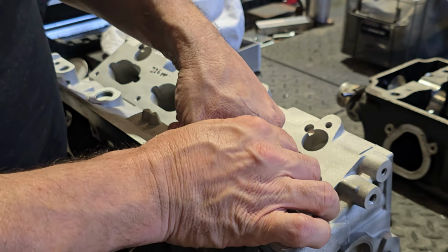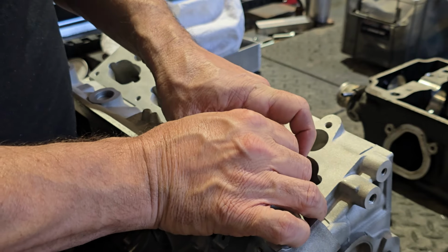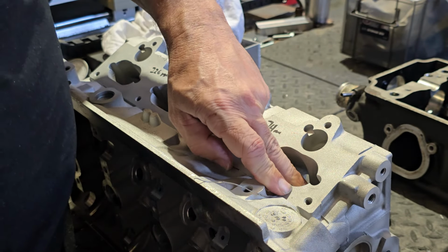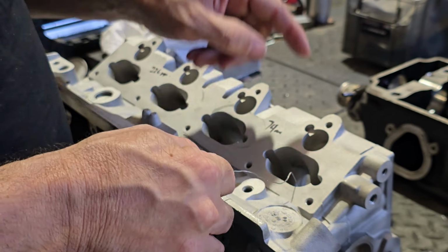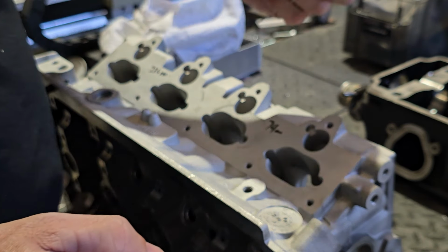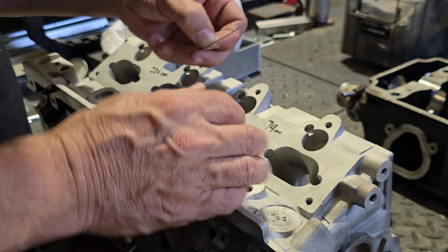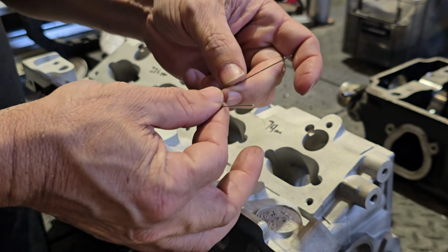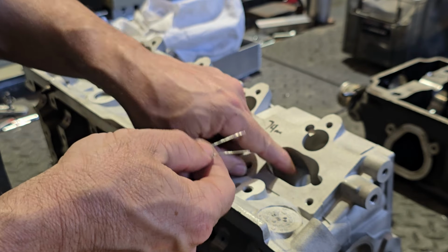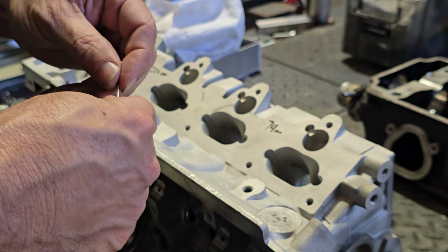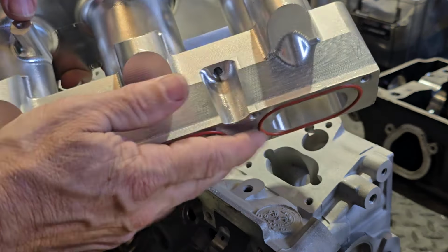So all I do is set it up on the bottom of the seat, and if you press it into the casting, it'll form itself, and then you can just bend it over like so, and then you've got the port shape. So we're going to do the roof and the floor. I've already done that now, so that's our roof length and our floor length. So we add those two together and then divide by 2, and that gives us our port length, which came up at 74 millimeters. Then we measured our manifold length.